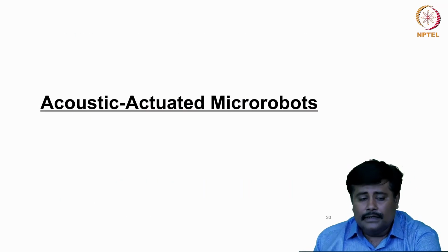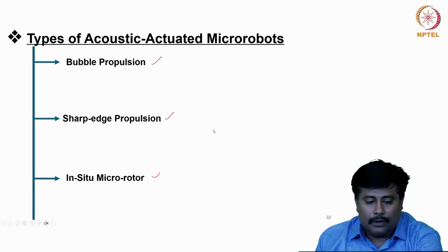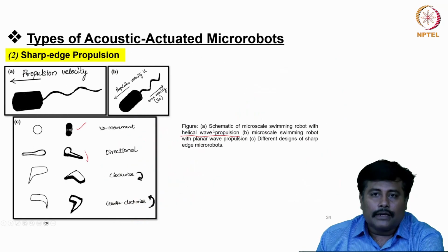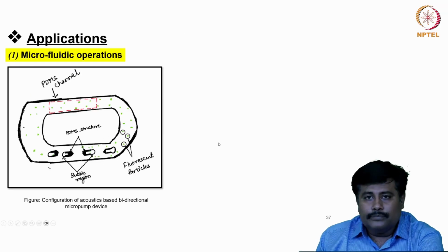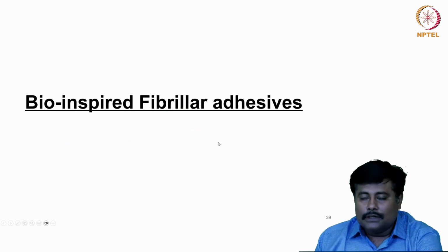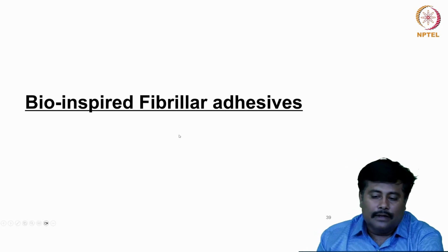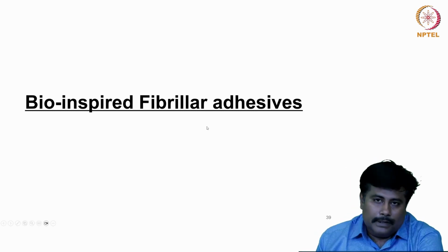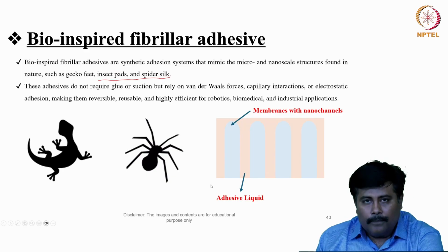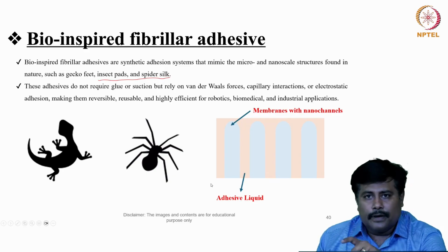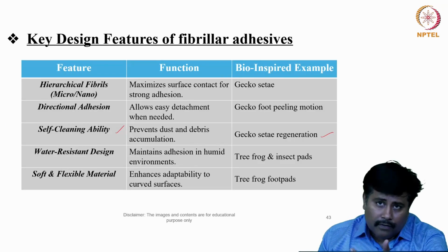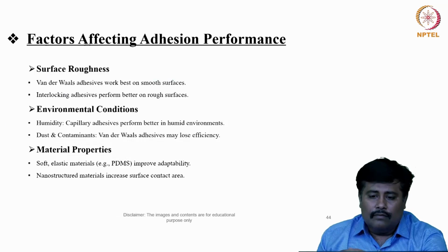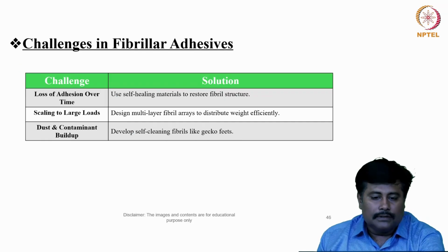We also had a detailed discussion about acoustic actuated micro robots, the types of acoustic actuated micro robots, the different challenges involved, and how they have been used for microfluidic and microsurgery related applications. One specialized adhesive technique is the bio-inspired fibrillar based adhesive. We discussed its overall configuration, how it looks, how it can be implemented, and the different functions of these bio-inspired structures.